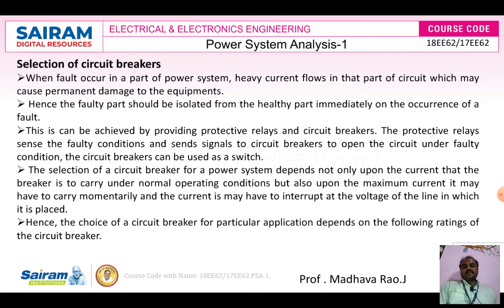The selection of circuit breakers for a power system depends not only upon the current that the breaker has to carry under normal operating conditions, but also upon the maximum current it may have to carry momentarily and the current it may have to interrupt at the voltage of the line in which it is placed.